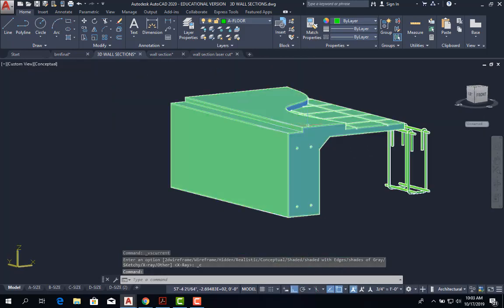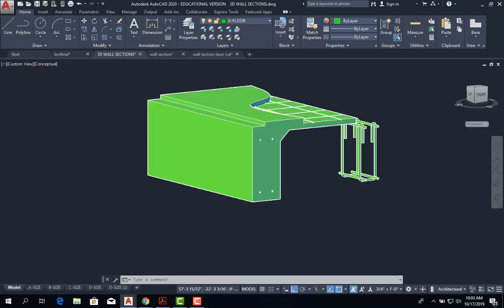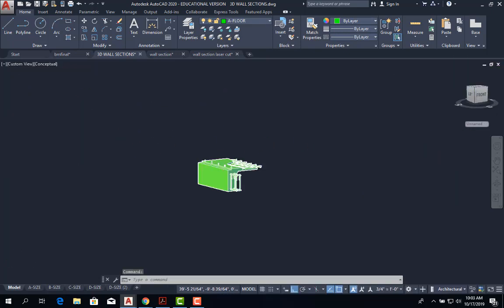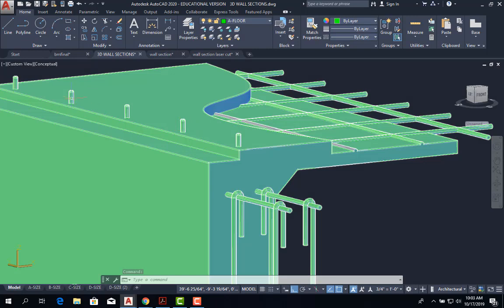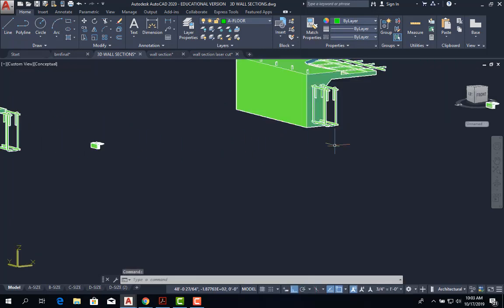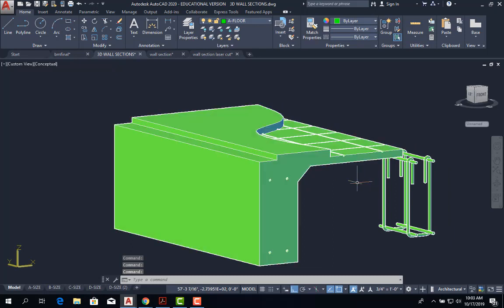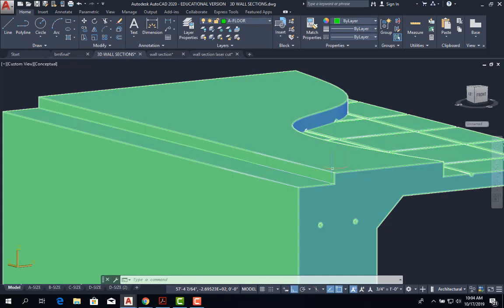All right. So your sole plate is going to be, this is your brick ledge, right there, and your wall is going to start right here. So that means you're going to have a sole plate right there. I don't have the J bolts. See, this is the J bolts. But since I'm not giving you the actual template, you won't be able to cut them exactly so you sit the plate on it. So I just got rid of it. Okay, so you're going to receive this as a 3D model already printed, and you're going to sit your sole plate right here, all the way.